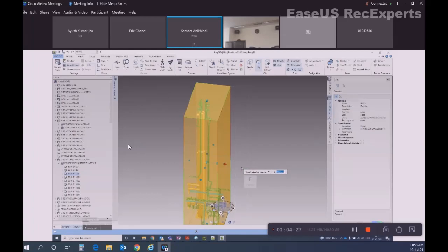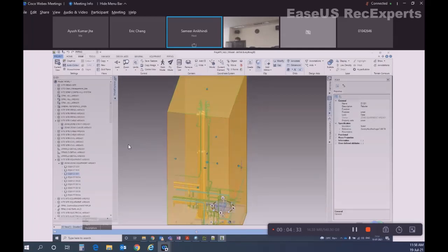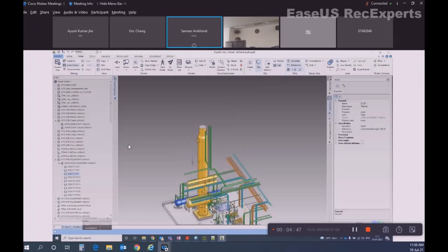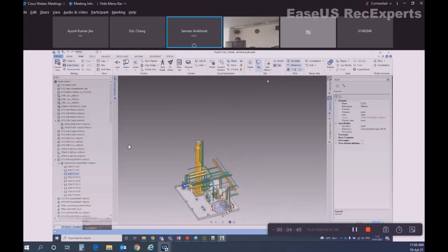Drop down, expand E. You want to increase the box by 2500 in all aspects. So this is how it is increased. Once you are done, you can move the modify box and start working wherever you were working. To bring back everything that was clipped, just uncheck this clip.